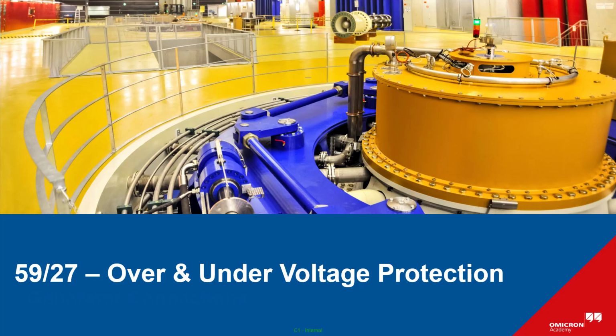In this video we will be exploring the overvoltage and undervoltage protection, commonly known as 59 and 27 in the ANSI code of protection. This protection plays a vital role in maintaining the safe and reliable operation of the generators and their connected systems. Mainly, the overvoltage protection helps to prevent insulation damage and overexcitation, while the undervoltage protection protects the connected loads and auxiliary systems during low voltage conditions.